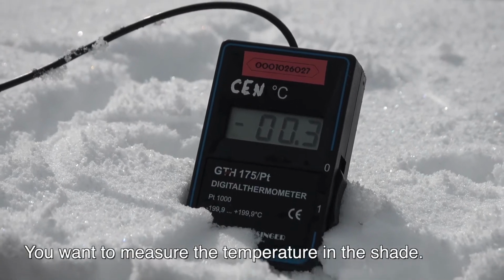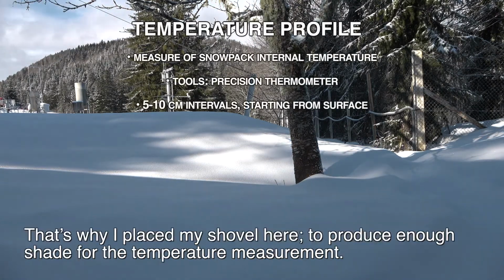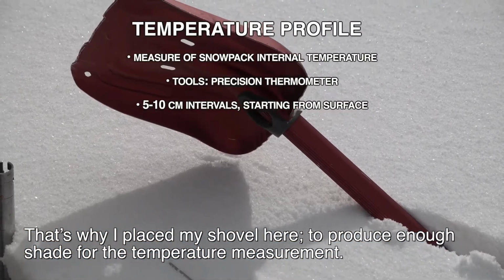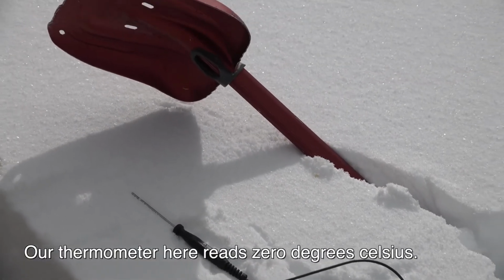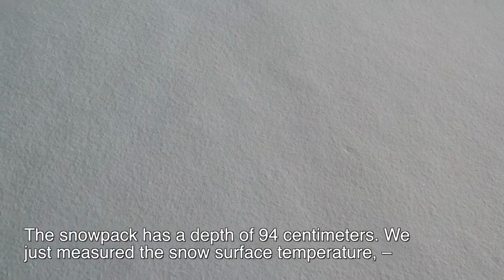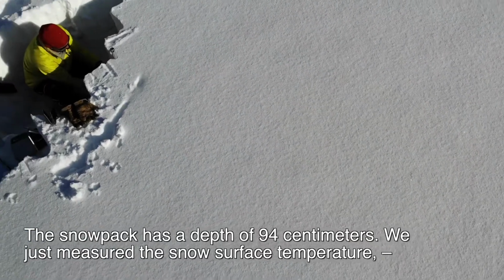And you want to measure the temperature in the shade. That's why I placed my shovel here, to produce enough shade for the temperature measurement. So that's the first temperature we're going to write down, and our thermometer reads here 0 degrees Celsius. So we got 94 centimeters of snow. So the snowpack has a depth of 94 centimeters.